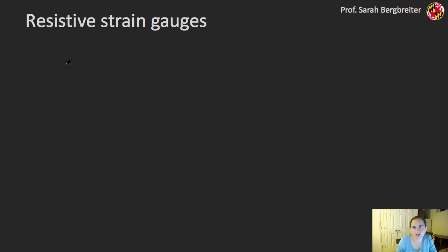microstrain. To measure strain, we're going to use strain gauges, and often you see it written as GAUGES or GAGES. But those resistive strain gauges are fairly similar, in some sense, to the beam that we just analyzed. It's a chunk of something. In this case, I'm going to give that chunk of something a length L. Oftentimes they're metal. It'll have an area A.